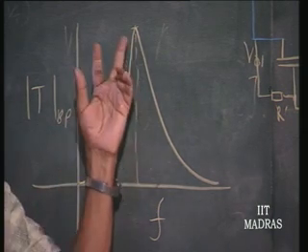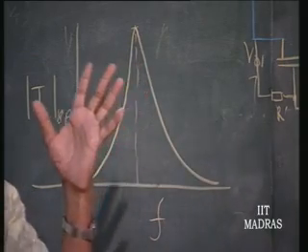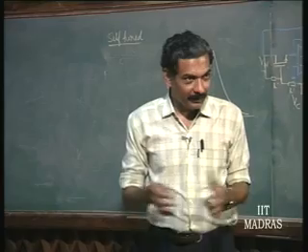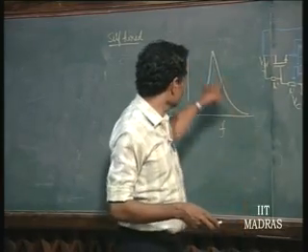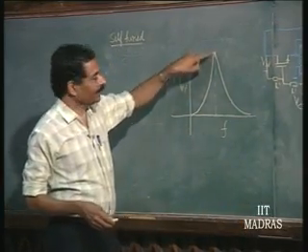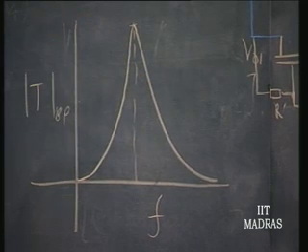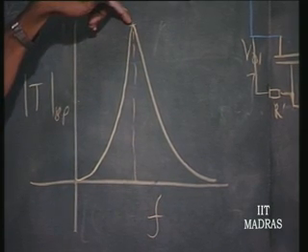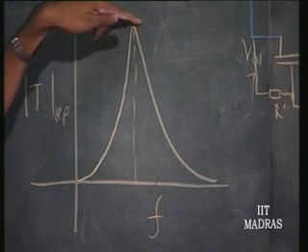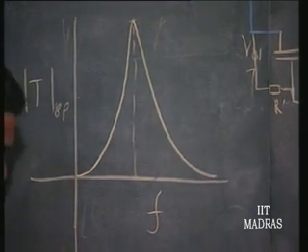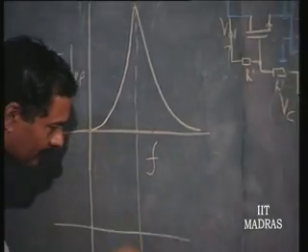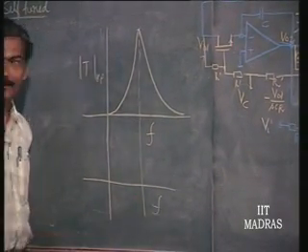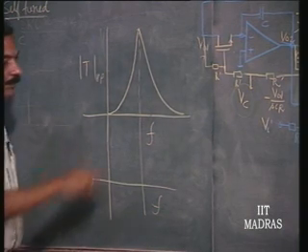Whereas, in order to find out whether around that frequency it is tuned or not, something has to vary by a great extent. So, this is something that, even though it is visible for a high Q circuit, is the wrong method of tuning, whereas we should make use of another parameter, that is phase variation with respect to frequency. How does phase vary with respect to frequency for a band pass?